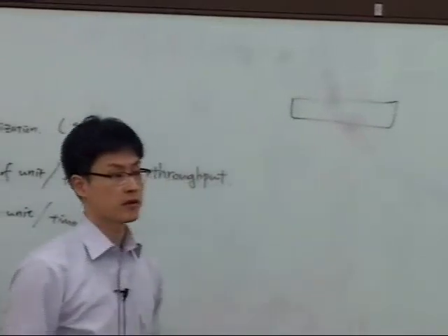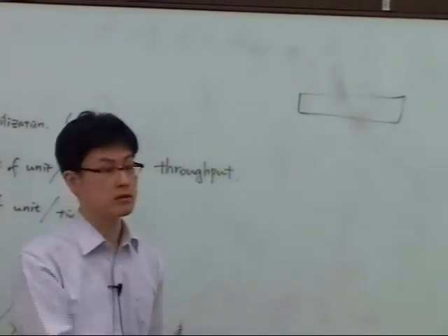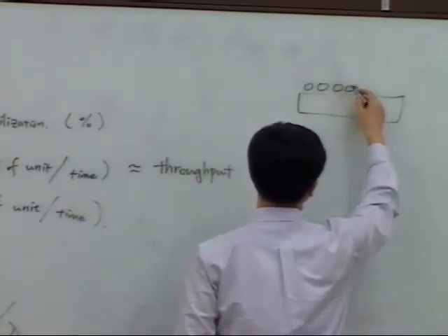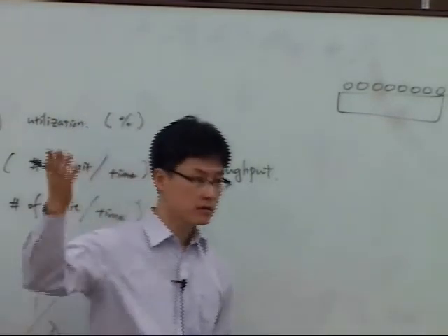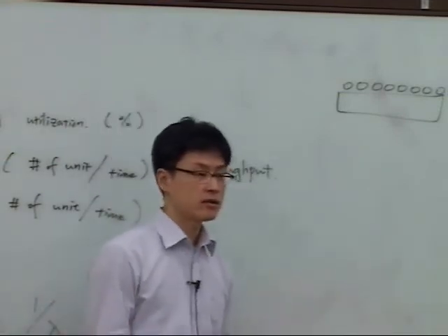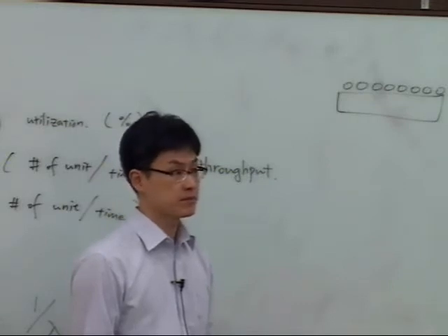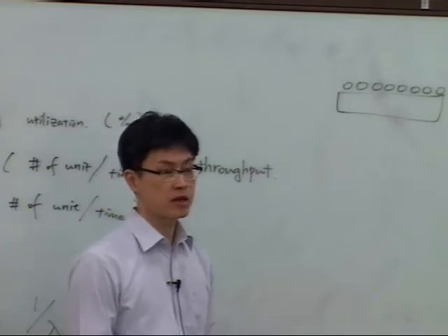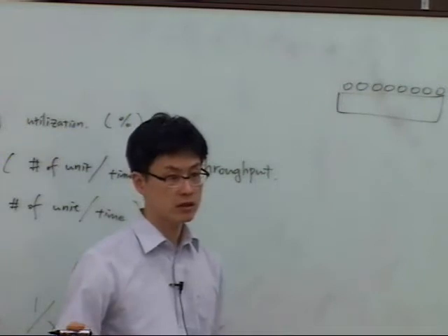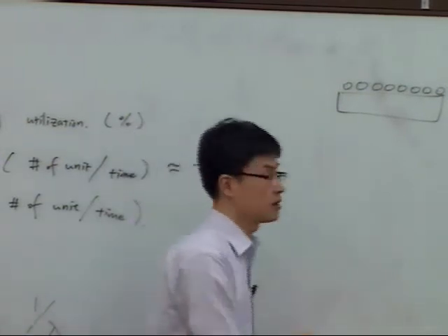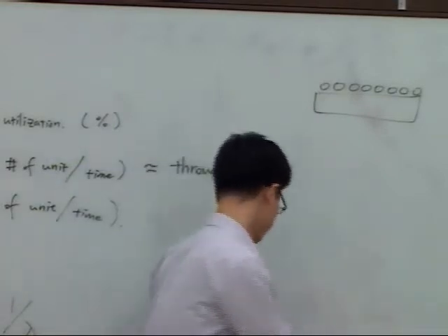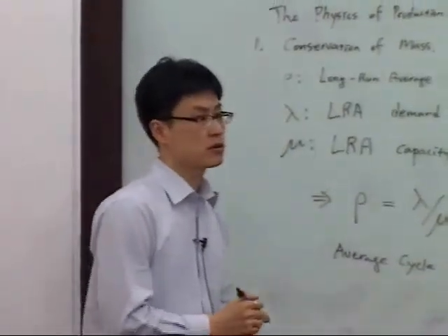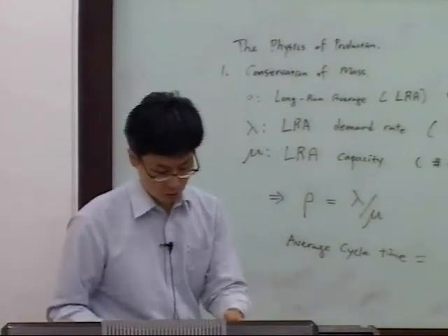Okay? Let me explain in this way. This is your factory. Your factory has some kind of conveyor line. Let's say this is an automobile. Okay? Car after car after car after car. So in Hyundai Motor Company, the Sonata comes out every 3 minutes. This is the cycle time, which does not mean that the build time is 3 minutes. Build time could be 2 weeks or a month or so, okay? But when Hyundai Motor Company manufactures only one product, then, yeah, okay? Really important: if you get confused about build time versus cycle time, then you will get lost, okay?